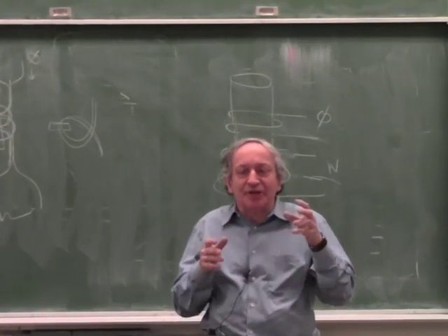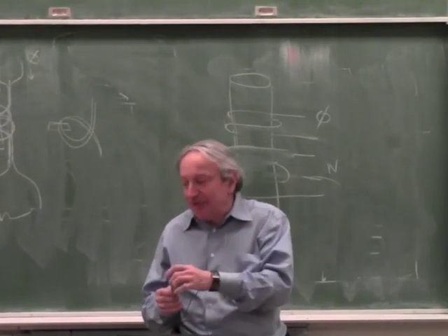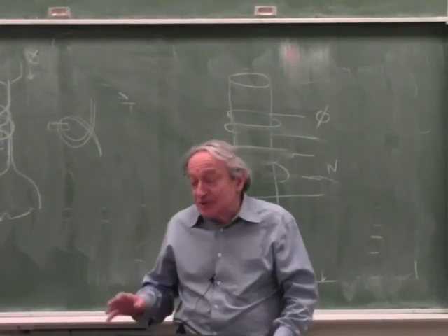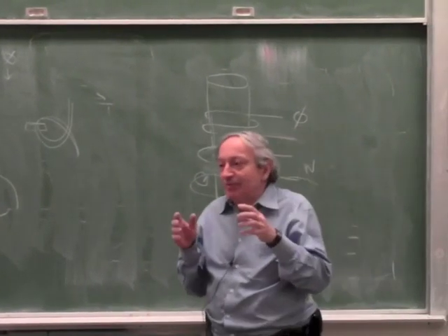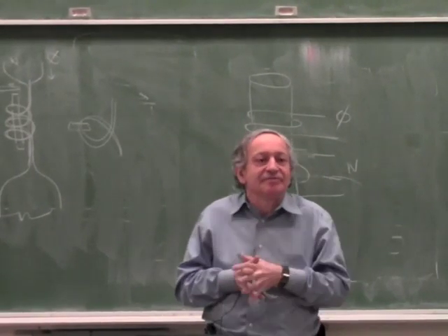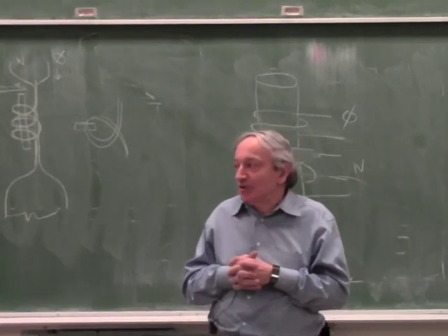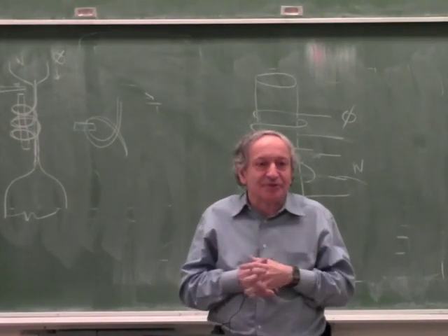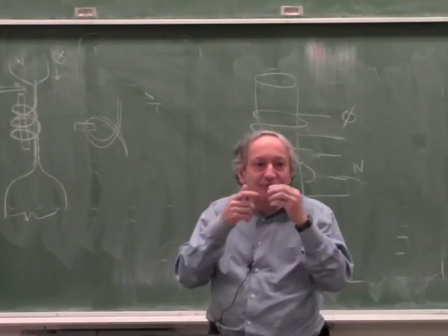If you look at high-end connectors, even a BNC, if you look at the inner pin, it's gold-plated. Any high-end connectors, not just for RF, are gold-plated, but in RF stuff, when you open up high-frequency equipment, everything is silver-plated and gold-plated inside. Yes? Okay, number one, corrosion resistance, because gold protects it. Silver, by the way, is not so good for corrosion, but gold is the best. So number one, corrosion resistance, you want good contact.